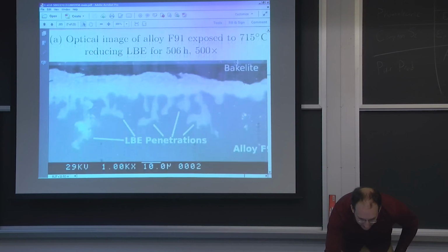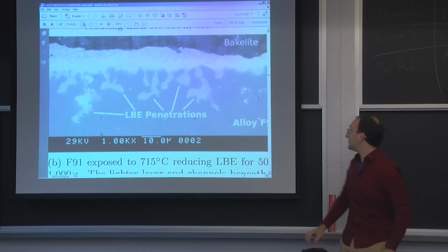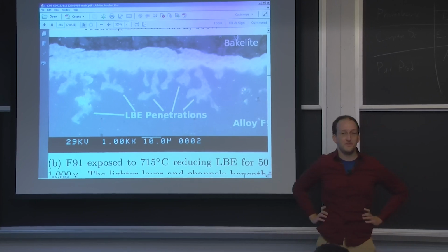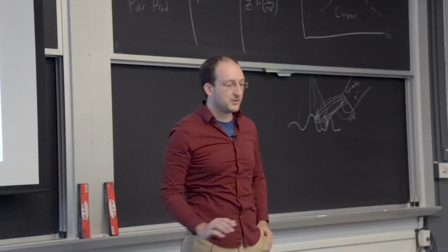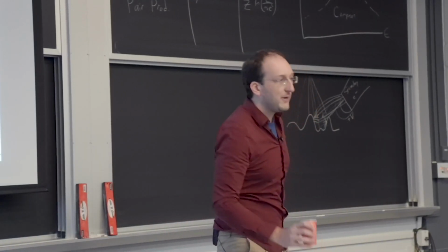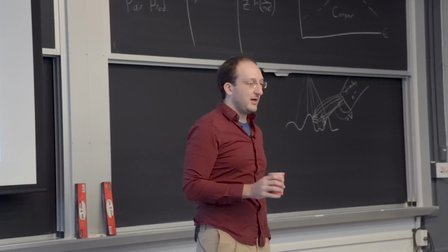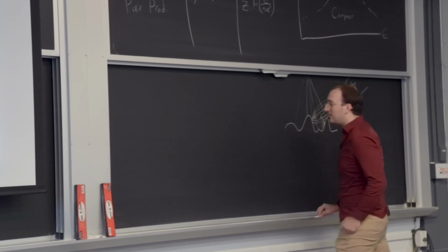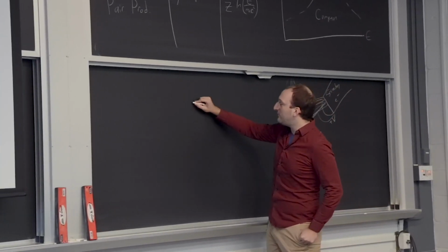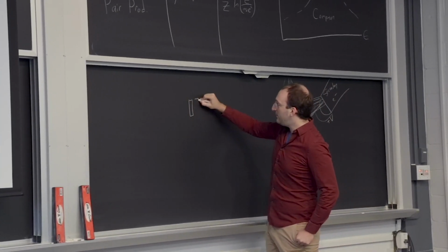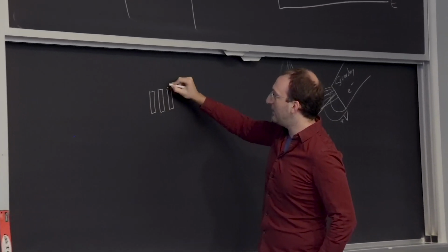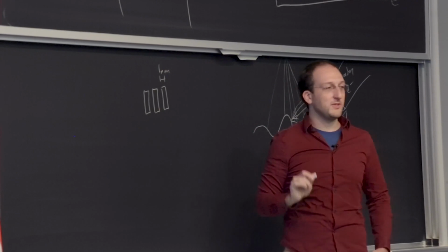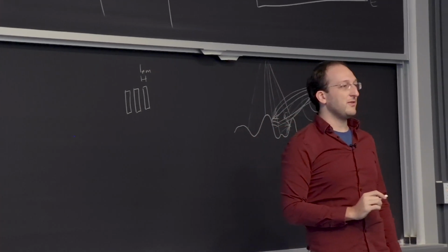Switch down to an SEM, and then all of a sudden the picture becomes much, much more clear. You can start to see things. The best SEM we have in our lab has an ultimate resolution of about 1 nanometer. Now, resolution is kind of a funny thing. It's neat to tell you what that means. It doesn't mean that if you have a pattern of lines that are exactly 1 nanometer thick, that you will see them as lines 1 nanometer thick.